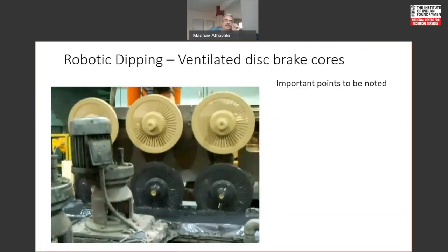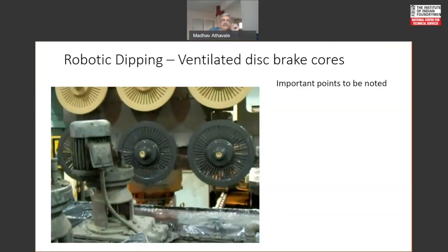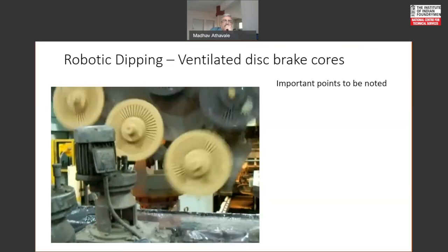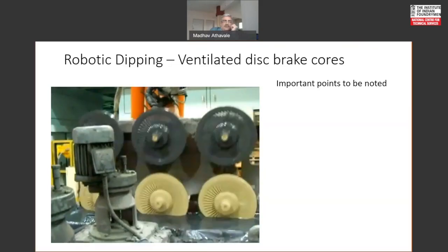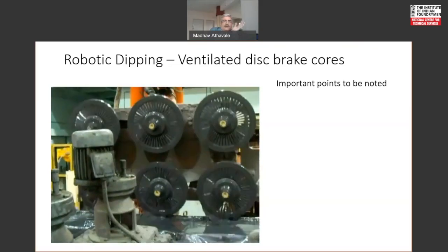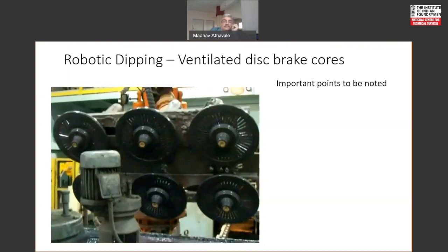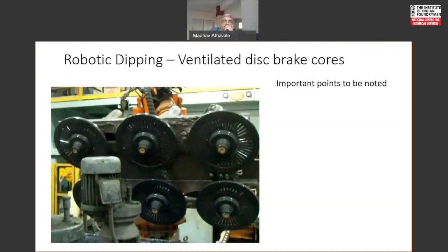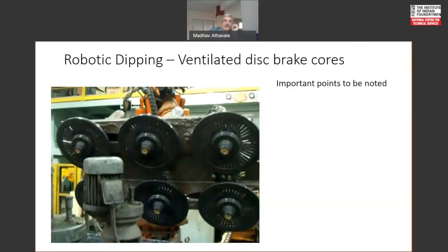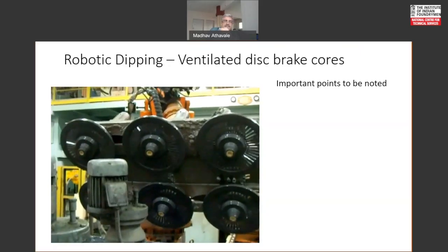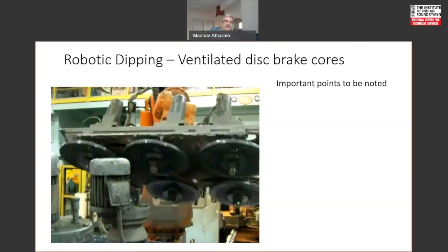Then they are spinning, they are rotating as they get dipped inside the coating bath. Then the other two sets, so all of them are getting spun at least 3 times. It is also tilted to ensure that excess coating goes off, plus again it is spun again. And then it will be placed for drying immediately.